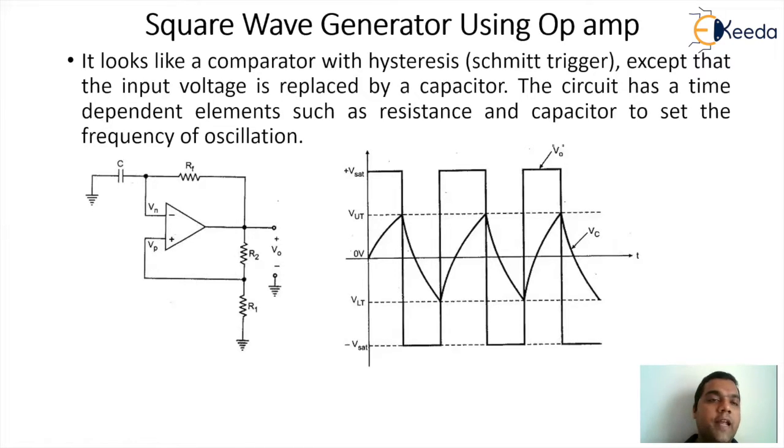Because the voltage is now negative, the capacitor will start discharging and losing energy. It can lose charge till the value of the lower threshold point. As soon as the voltage of the capacitor falls slightly below the lower threshold point, again the plus pin of the op-amp will become greater than the minus pin in terms of potential, and the op-amp output will become plus Vsat. So if your observation is sharp, we come back to the initial stage from which we started the operation. This operation will keep on continuing, where the output keeps switching from plus Vsat to minus Vsat, depending on the charging and discharging voltage of the capacitor.